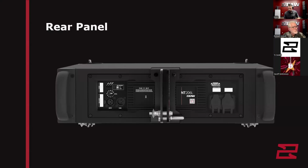All right, let's take a look at the rear panel, or a closer look at the rear panel. So as Robert mentioned, this is designed to be familiar connections. So we've got an analog input with a through. The through allows for fewer cables when deploying your system. It's a PowerCon TRUE1 input. This also has a through. This allows you to loop up to 2 additional modules, so 3 per circuit. There are connected covers to protect from the outside elements. There's a level knob, 3 indicators. There's a limit, signal, and power indicator for you to use for monitoring.